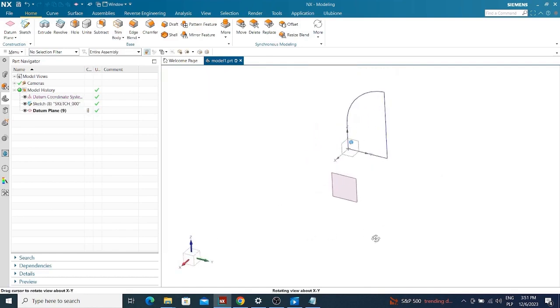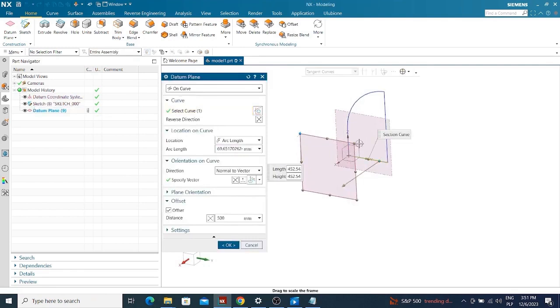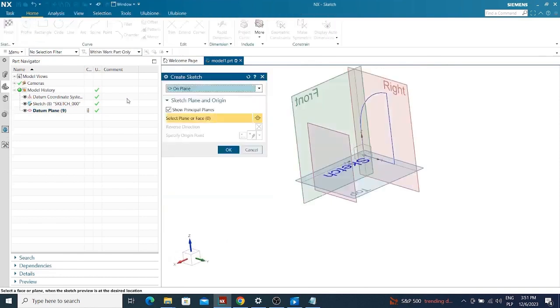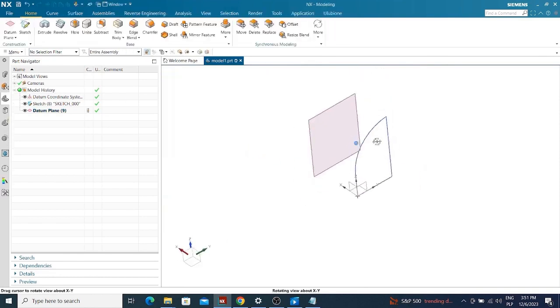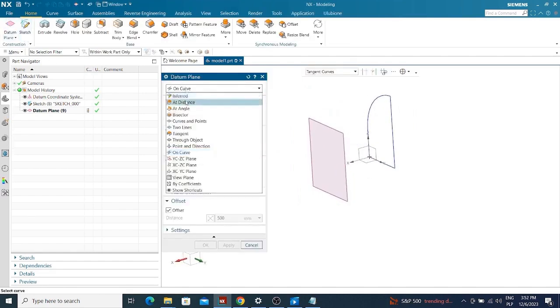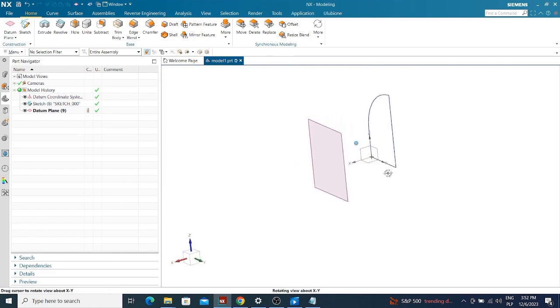This plane is of course kind of infinite. I can zoom in on the preview here and expand it, but it obviously goes on infinitely. Anyway, now, for example, I can choose a sketch. Of course, I showed you a slightly more complicated way of creating this plane because I could just as well have taken a datum plane, added some distance, selected that specific plane, and then moved it. There are a lot of options for creating these auxiliary planes, so I'll probably make a dedicated episode for them later. Now, returning to the topic of the sketch.